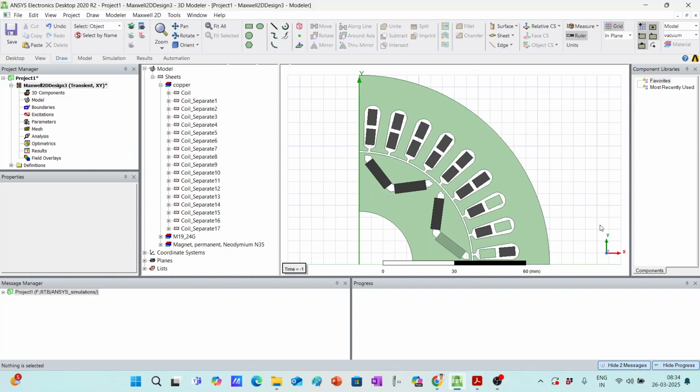Now the winding configuration you have to determine previously is a 36 slot 8 pole machine configuration, and a three phase machine. So for that, how the ABC phases will be distributed, you have to determine previously, and then you have to apply it here.